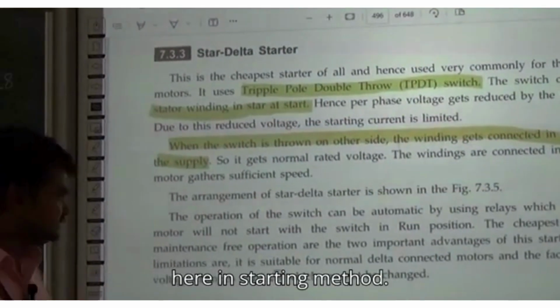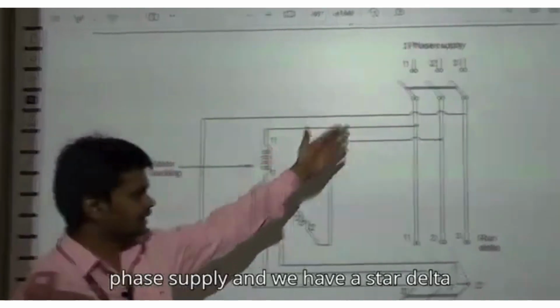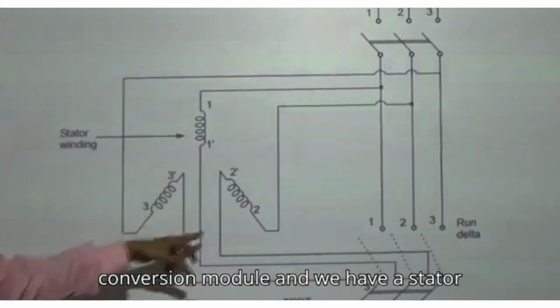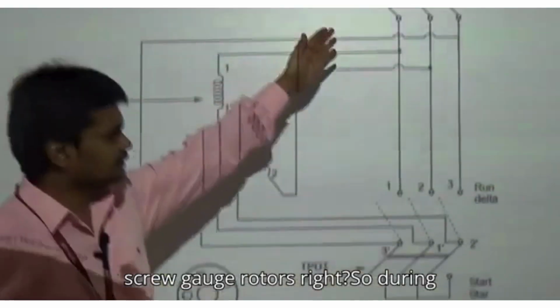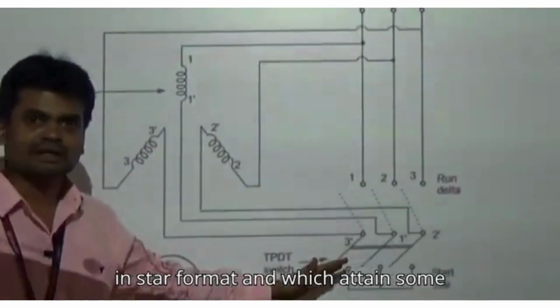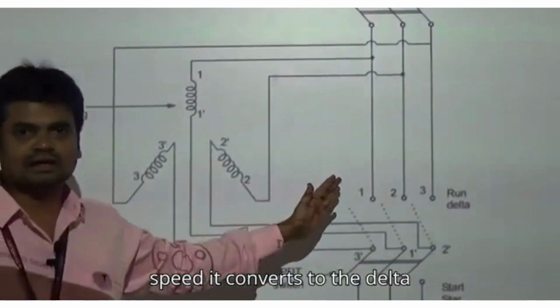Here in the starting method, from this diagram, we have a three-phase supply and a star delta conversion model, and we have the stator winding of the induction motor and the squirrel cage rotor. During starting, the stator is connected in star format, and once it attains some speed, it converts to delta.